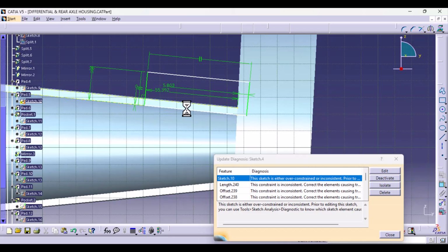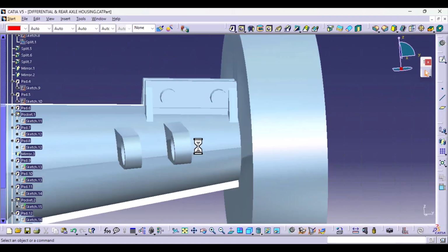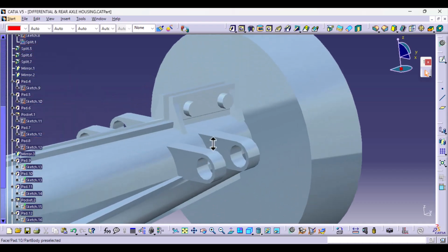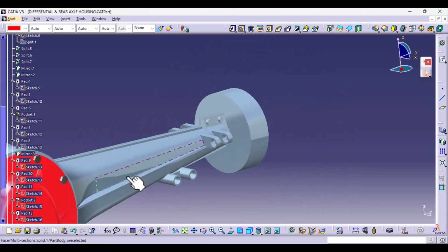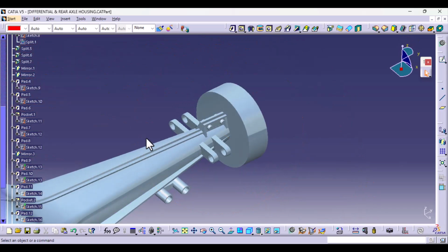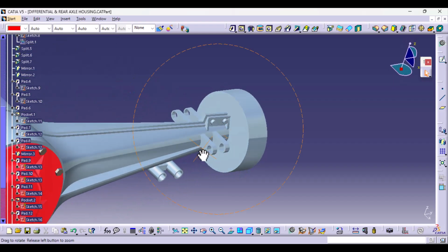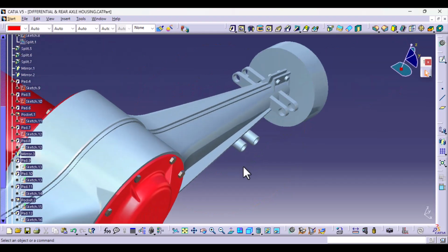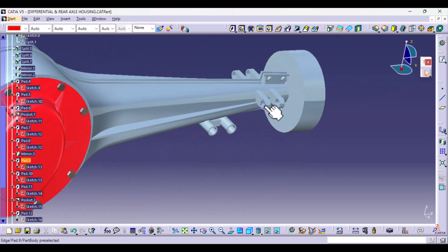Exit. Let's give it a moment to update. And now, as you can see, all our subsequent geometries have adjusted to the new diameter or the new width and height of the geometry, and that's exactly what we wanted. We wanted them to move like that. So obviously this sketch in the chassis assembly is constrained to the friction damper assembly, and it will just move relative to that.